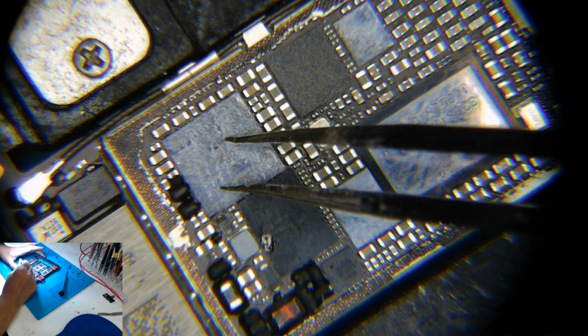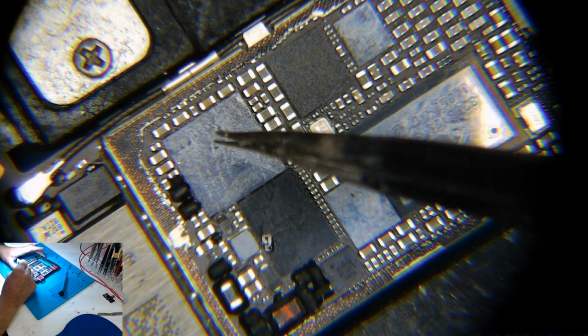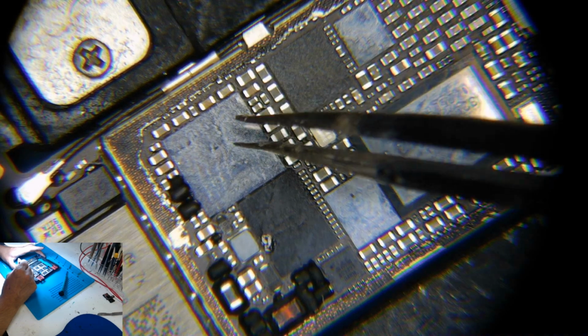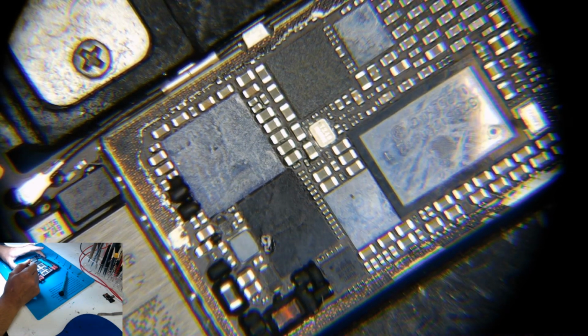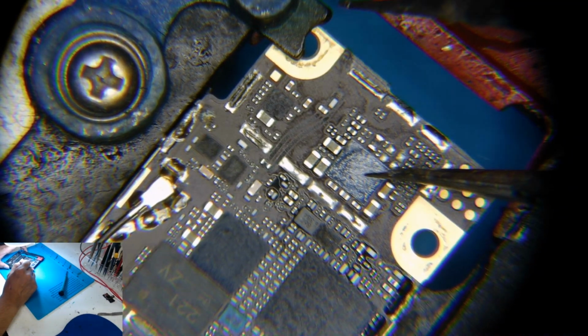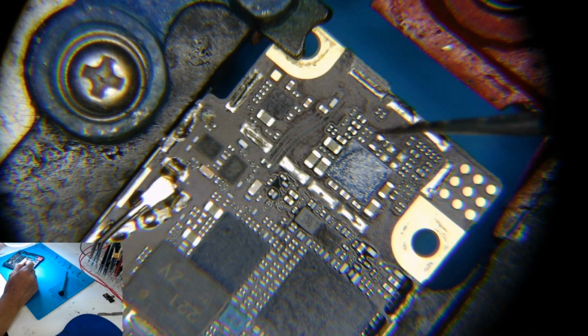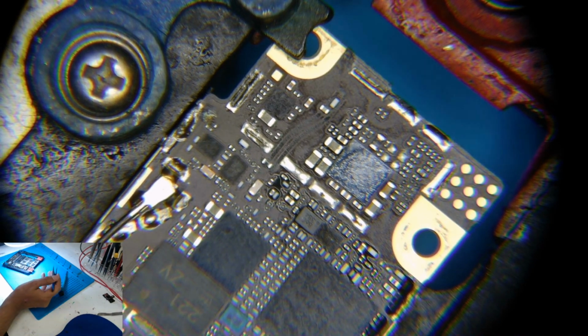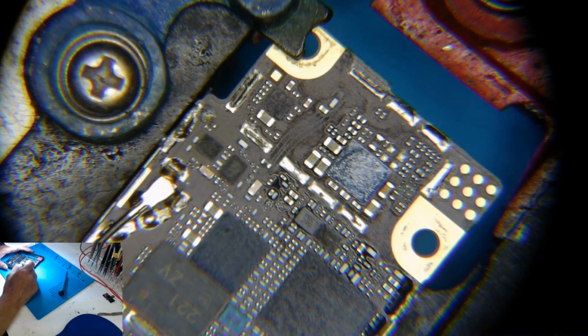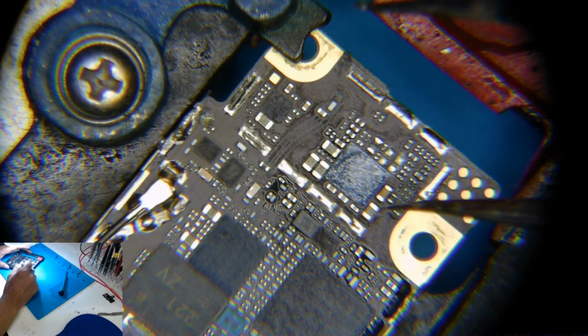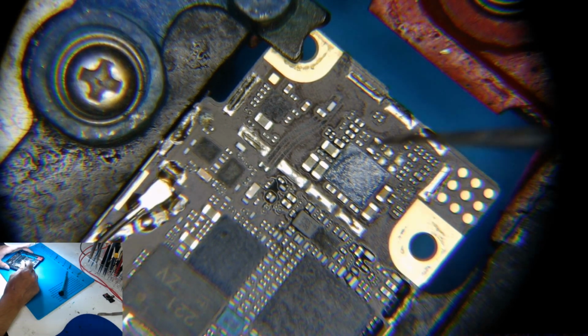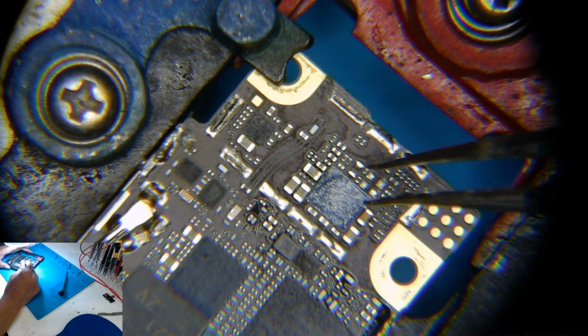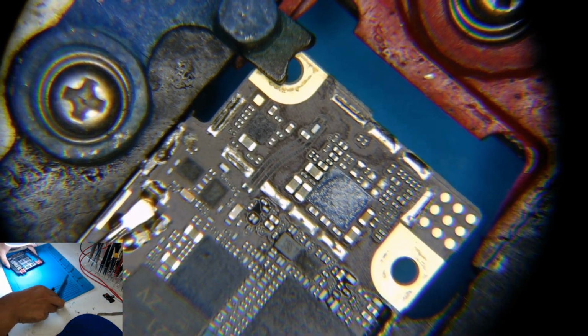I really don't think the problem is over here, because the speaker works, microphone works and everything, only the loudspeaker doesn't work. And because this is called the speaker amp, the small one, amp is amplifier, the loudspeaker is going to work through the amplifying, like maximizing the sound which comes out from the codec. So maybe I'm wrong. So what I'm gonna do is take off this one and measure all the voltage and everything from there, and if it doesn't work then we change the big audio IC.